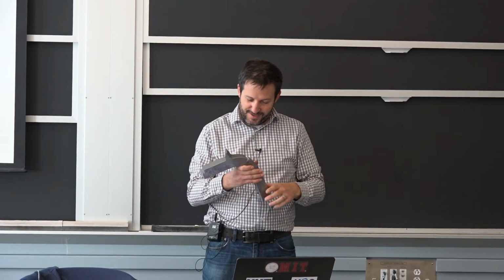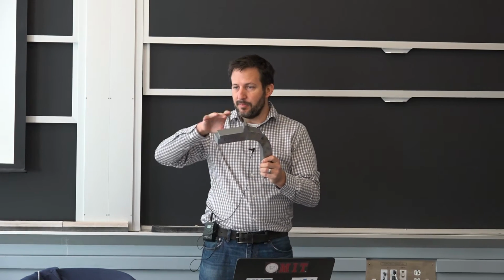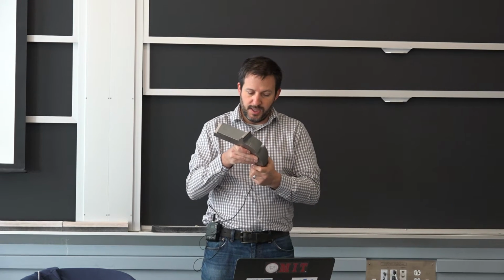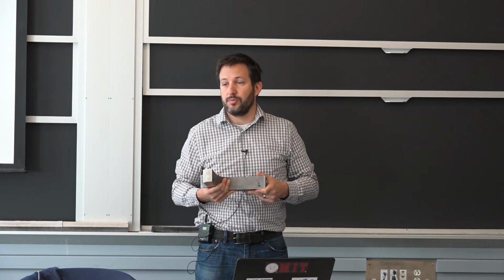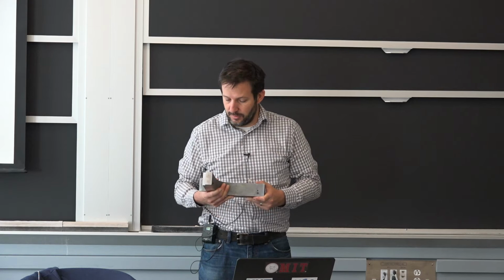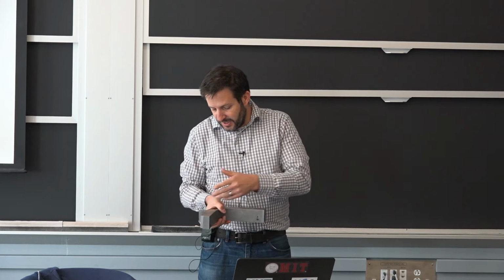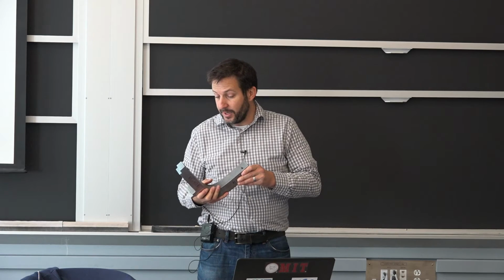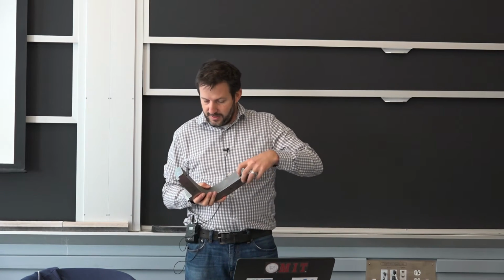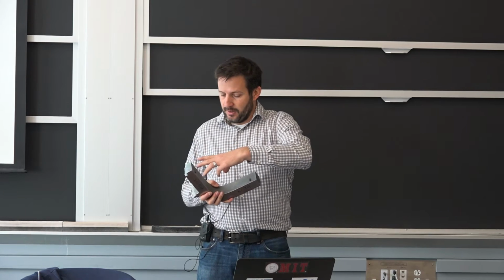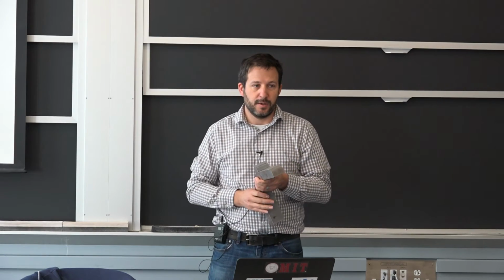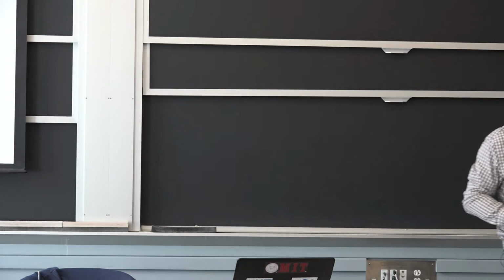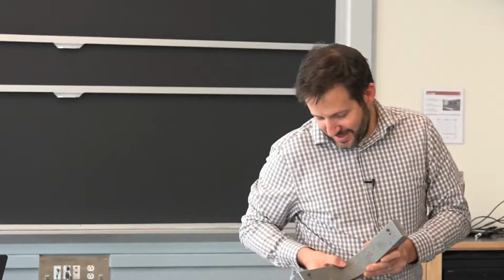Okay, one last thing is this was cold bent from a big plate. So you can see it here, and we made that notch because one issue they had was fatigue cracking at that bend, and we're trying to verify whether it was really cold form and the kind of stresses that they were getting. So we had a finite element analysis of this, and then to make sure the analysis was correct, we made this test where we had reference points, looking at the distance between the reference points, removing material, and getting that spring back that I've been talking about. So kind of an all-inclusive sample here.